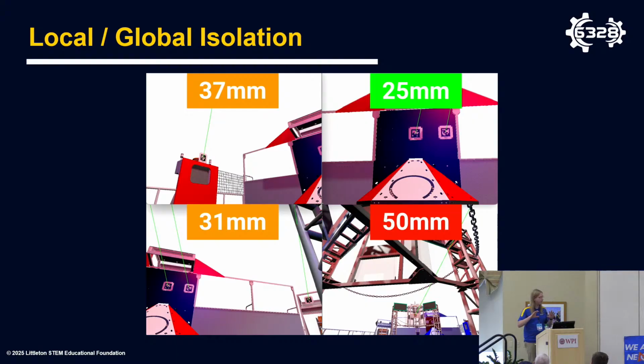So here, this shows an example frame from our 2024 robot when we're shooting into the speaker. And up at the top, you can see the calculated standard deviations. So lower numbers means we're trusting that camera more. And most of the time, when we're moving around the field, there's no reason to trust any camera more than any other. Remember, April tags tend to be very evenly distributed around the robot.